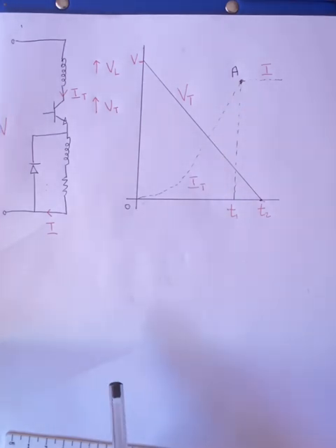So for now, we've discussed snubbers, pointing out that there are two different types. We've shed light on the fact that this circuit diagram is that of what is known as a turn-on snubber. We also pointed out that snubbers are essentially used to keep transients within the safe limits of a device. Snubbers delay the rate of rise of either voltage or current in a device, and this is fundamentally used to minimize the power dissipated during switching times by means of wave shaping.